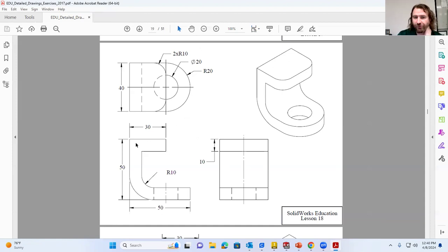So really the front view, this shape, is going to be the best one to start from and be able to get the shape, extrude it 40 millimeters, and then fillet what we need to fillet and cut out that hole. So a bit of an interesting one as far as choices goes, but because it's this shape and then extruded for this distance, this is the best beginning location, this front view. So that's what I'm going to do.